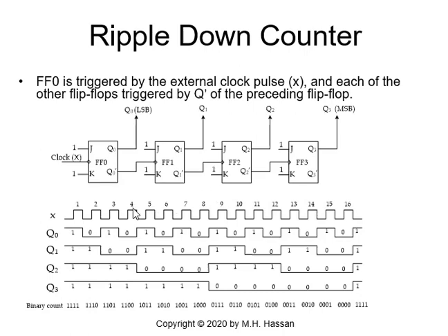And here we will have X, the clock pulse. We have 16 clock pulses shown here, and Q0, Q1, Q2, Q3 are initially all ones. So at the negative edge, Q0 will move from 1 to 0, 1 to 0, 1 to 0.